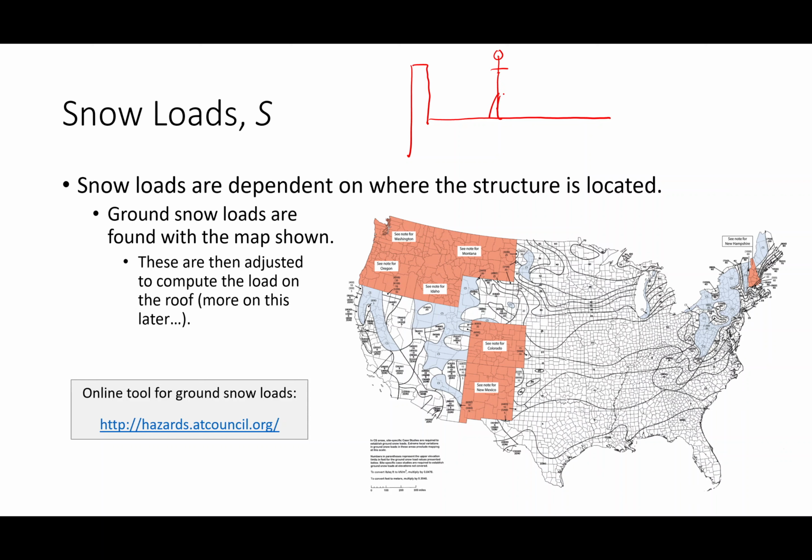There's you. Okay, so you get a little bit of snow on the ground, right? And then the wind blows, and you get a bunch of snow that piles up here on this barrier. And it's almost like you get this triangular load that you put on a beam, that Dr. Mike said, yeah, you deal with triangular loads. And you're like, no, you don't. I'm like, there you go. Here you do. So this is an idea of the different things that you have to consider with snow loads.